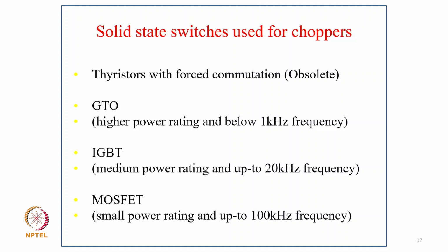Earlier we were using thyristor-based force commutation, which is now obsolete because force commutation had additional cost as well as reliability issues. Sometimes commutation failure occurs. Apart from that, it limits the switching frequency. So now people are not using this.